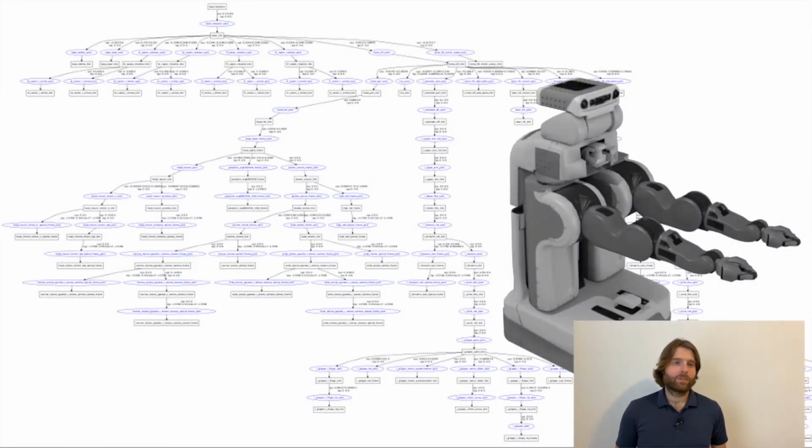As you can imagine, as your robot grows in complexity, you can end up with very complex XML trees that define your robot through URDF. Here's a visualization to give you a sense of how large that can grow with the PR2 robot by OSRF. To help make these more complex URDF files easier to read, modify, and extend, you can use something called a Xacro. To briefly introduce Xacros, I'll demonstrate two capabilities: setting reusable properties and defining a macro.